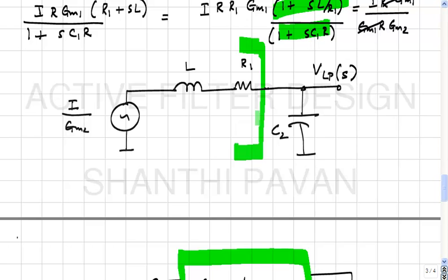So the inductor current here in this network corresponds to which voltage? The voltage across C1 in the GMC network. Is that clear? Okay. So in other words, if you interpret the GMC second order section as emulating an LCR series network, then you can interpret the voltage at the band pass node as being proportional to the current through the inductor in the series RLC network.